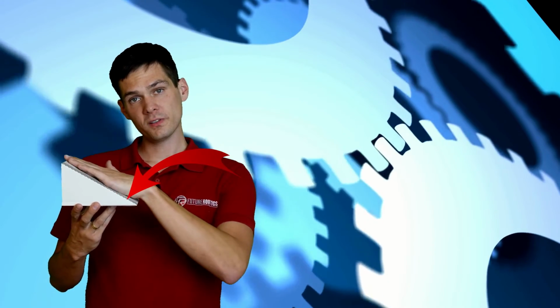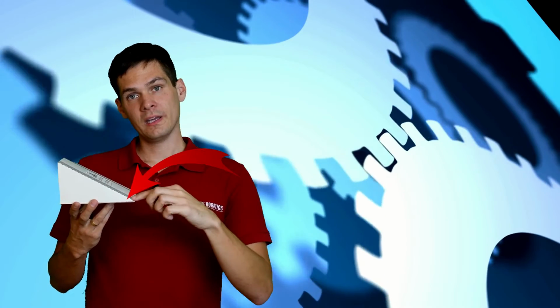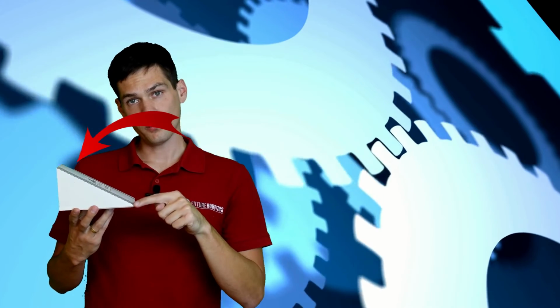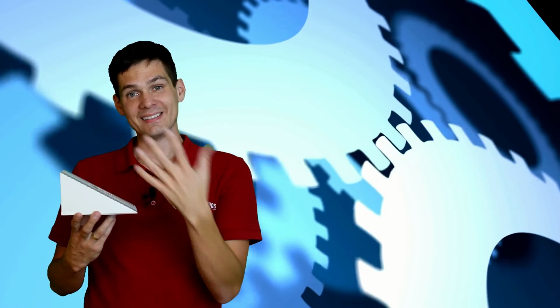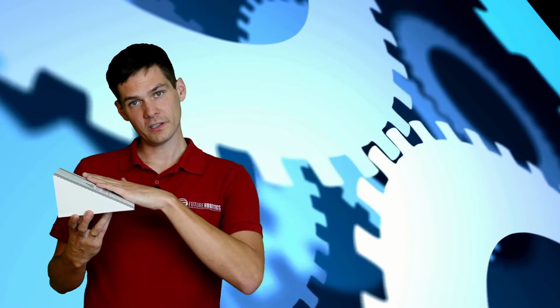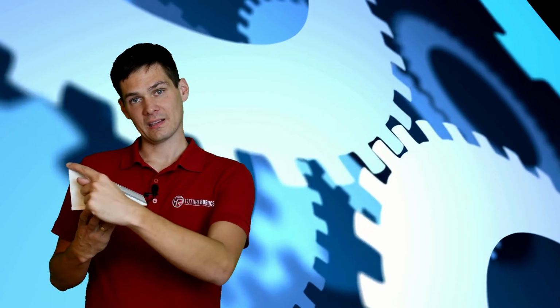Now, because for you this is going to be a flat surface on an angle, if you move here, that distance from here to here is going to be calculated, instead of being calculated from here to here on a random angle. Well, not random, you will know it, but on an angle that you don't really want to have. And it might be a little bit misleading information. So if you teach the base in here, and that's your 0, 0, and you go here, probably that's going to be, let's say, around 18 centimeters, so 180 millimeters.